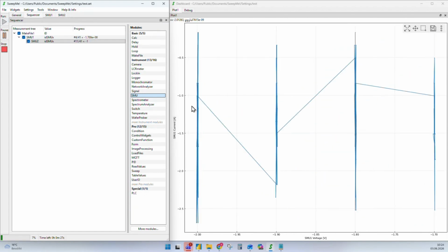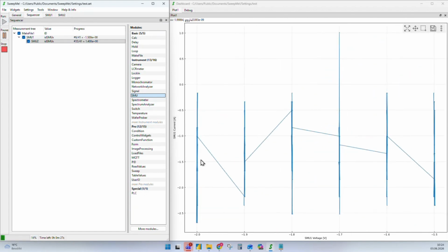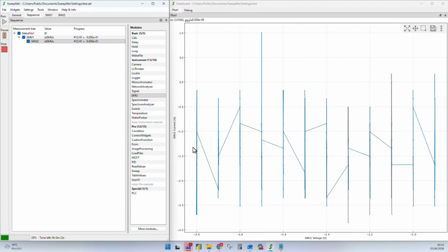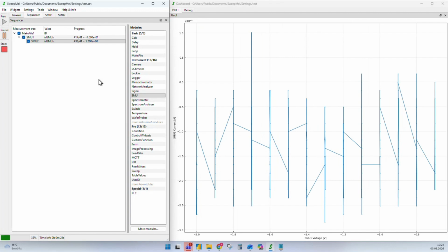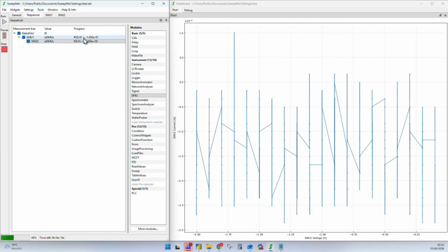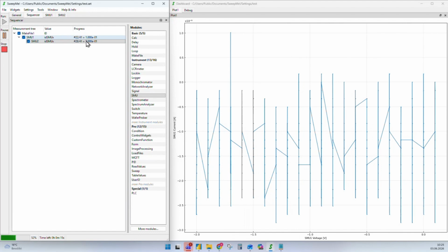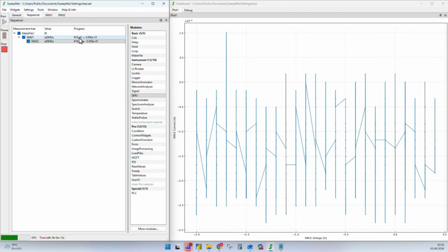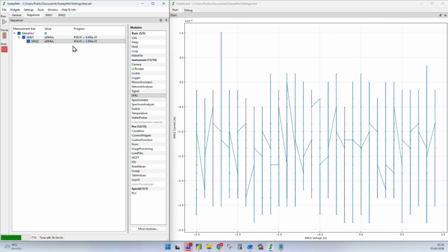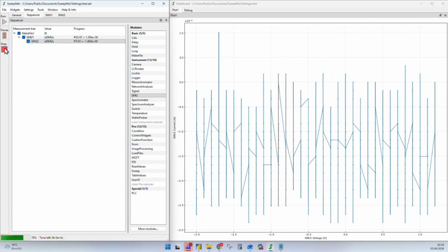And what we see is that at each point of SMU1, the second SMU makes a complete sweep. Because there is no transistor connected, but just two LEDs at each contact, this does not make much sense. But you can see that we are going through this parameter space of the combination of around 41 values for the first channel and 41 values for the second channel.